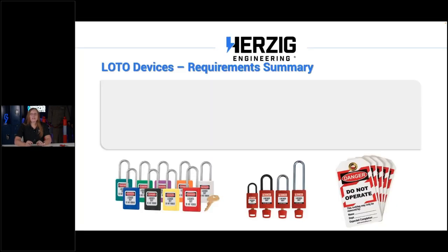For those locks and tags specifically, because those are going to be the most commonly used on pretty much every LOTO procedure, there are times where you can just use a lock and no tag, or a tag and no lock. It's based on company policy. You have to keep a robust decision on that though. Most of the time, the vast majority of the time, do both together.